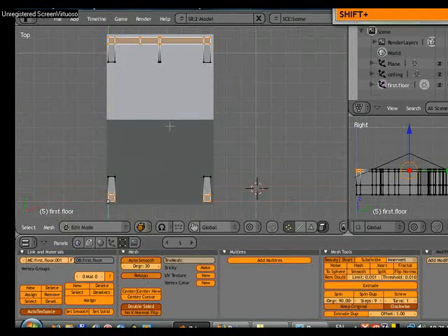And you can see what's happening on this right view on this part of the screen. So I will be in top view. It's important because the retopo works down from the way you look, and I want those vertices to go down in the Z direction. So I'm looking down in the Z direction, and I'll press retopo and retopo all.